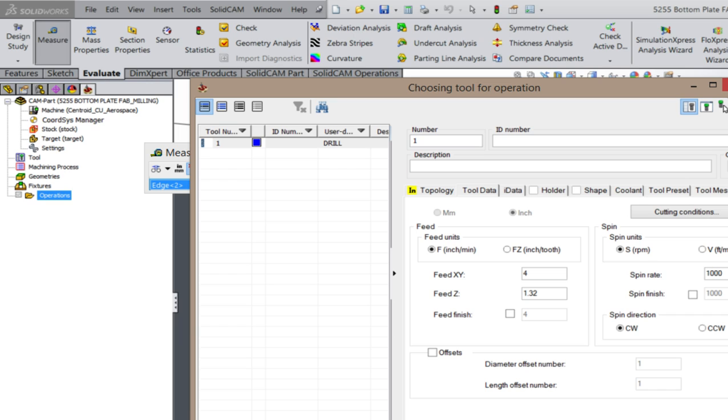No, if you're going to tap it, you're going to do it by hand. With the pecking, but what axis is the pecking on a drill bit? That's Z. So in X and Y, all that feed is how fast it's going to move from one hole to the other. And in that case, we can go as fast as we want because you're not cutting anything. You're just moving in air.